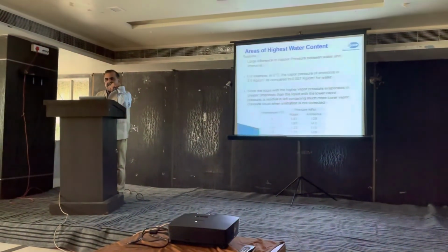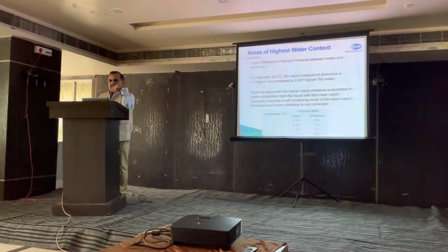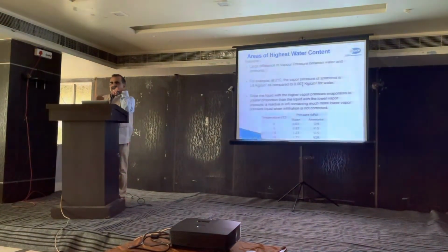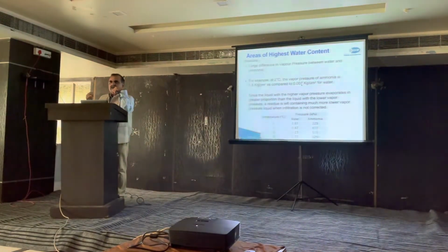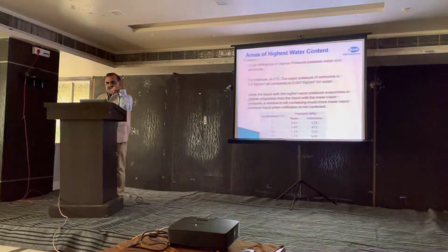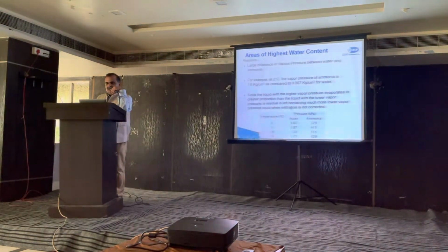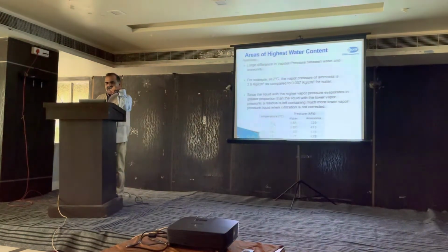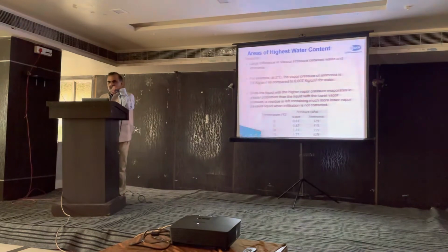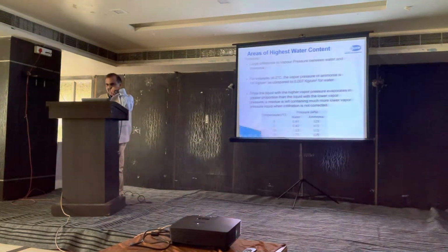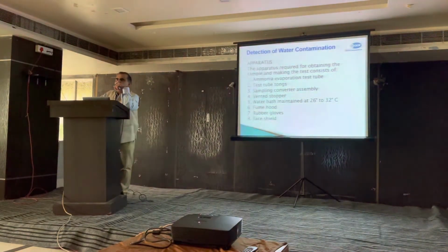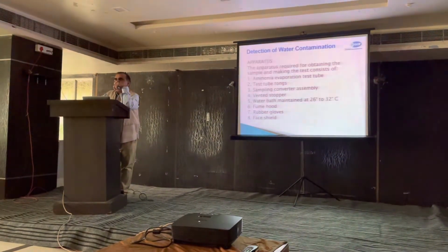For 2 degrees centigrade, ammonia pressure is around 3.6 kg, whereas the water pressure is 0.07 kg. So when the ammonia is evaporating at 3.6 kg, all the water will remain in the evaporator. This chart shows us the water pressure and ammonia pressure at various temperatures. If you see, the difference is so high that water will always remain accumulated on the evaporator side. It will not evaporate.